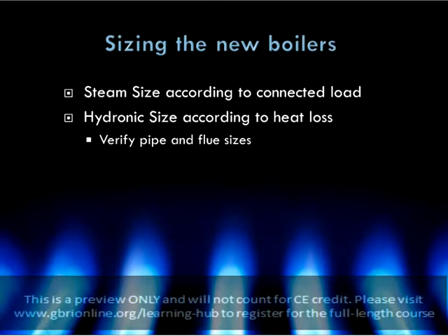If you performed a heat loss on that building, your heat loss may only be 1 million BTU. But with steam, you really have to size it for the connected load, because the radiators don't care what the temperature is.